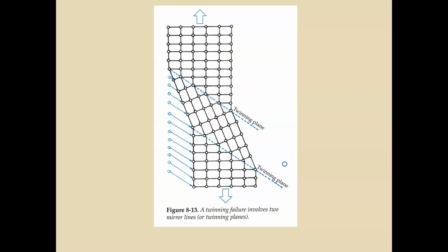First, for slip, the crystallographic orientation above and below the slip plane is the same both before and after the deformation. For twinning, there is a reorientation across the twin plane. In addition, slip occurs in distinct atomic spacing multiples, whereas the atomic displacement for twinning is less than the interatomic separation. Slip occurs on relatively widely spread planes, but in the twinned region of the crystal, every atomic plane is involved in the deformation.